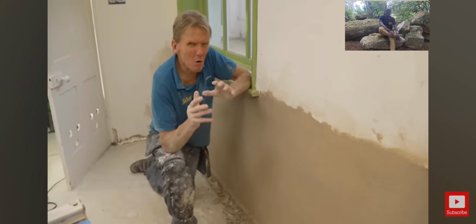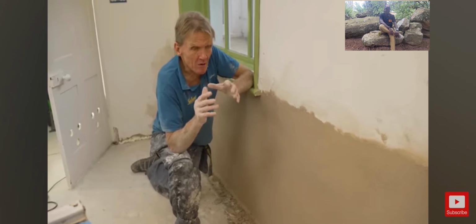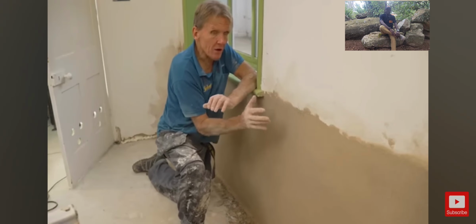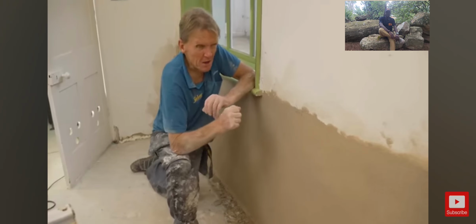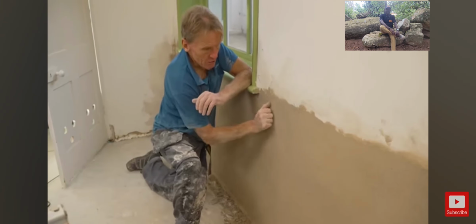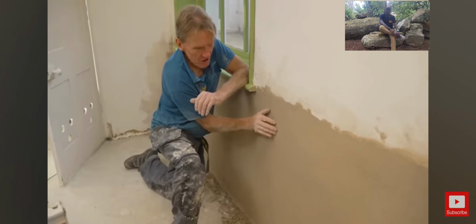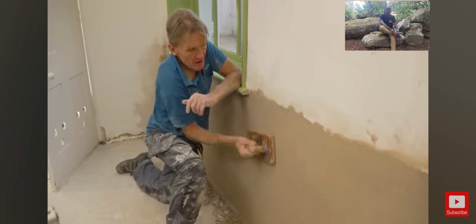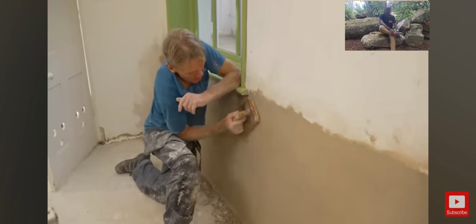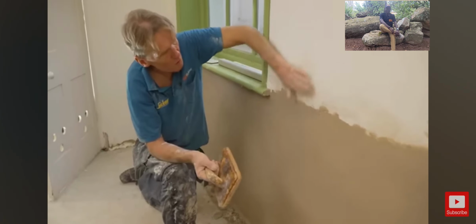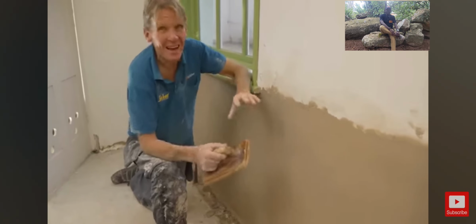And that's because it's more like render. And if you go on it too soon, you will get those bubbles, but it will pull back on its own, and probably in about 3 hours time, it will be ready just to close in with a steel trowel, just to get rid of this grittiness. Because what I did is I sponged it all up just to close the holes up, and it's made a reasonable finish on it, but that wouldn't be what you would call a plaster finish. It's not as smooth as that.